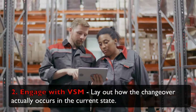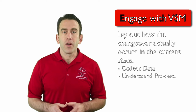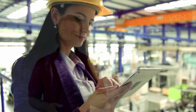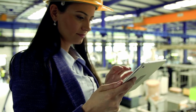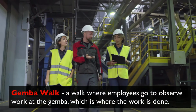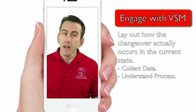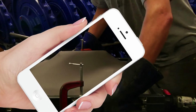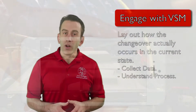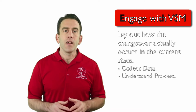The second step is called Engage with Value Stream Mapping. Now that you have decided what data you will collect and the team is focused on objectives, it's time to lay out how the changeover actually occurs in the current state. This is where you will want to collect the data you decided on in phase 1. 3 very effective methods that help reveal the current state are walking the Gemba, mapping the value stream, and videotaping it. Videotaping can allow you to slow down or speed up the process in order to see everything that is going on. What we hope to gather here is a complete understanding of the process in its current state. If inspiration hits for improvements, place them in a parking lot until the time is right and all elements of the changeover have been taken into consideration.